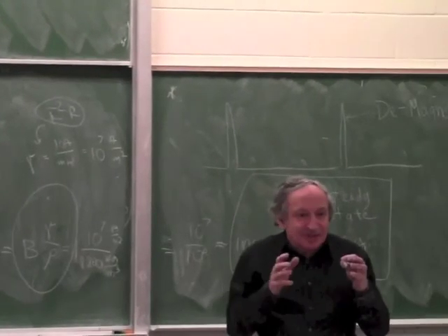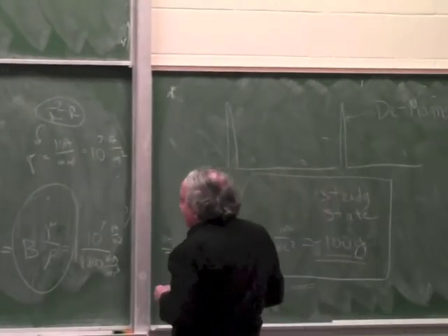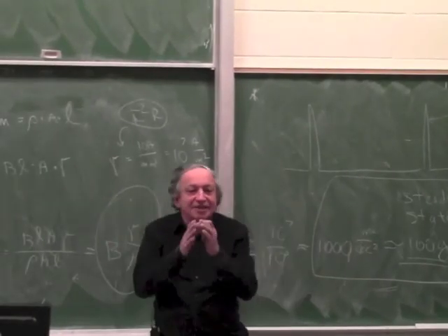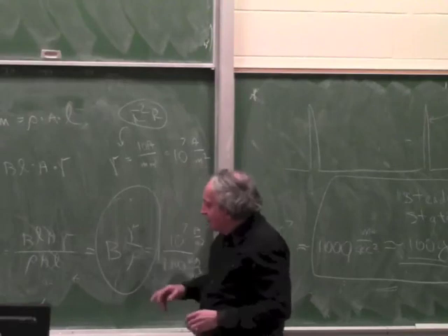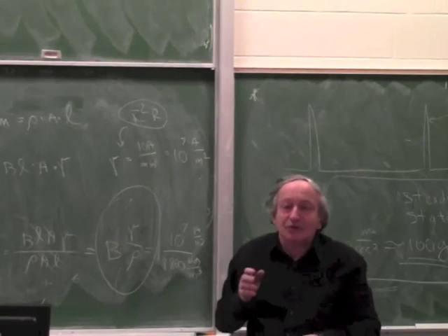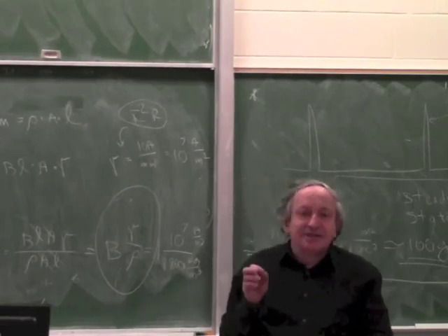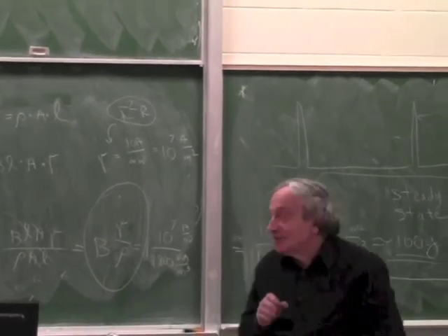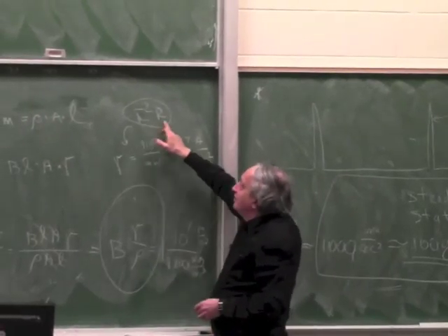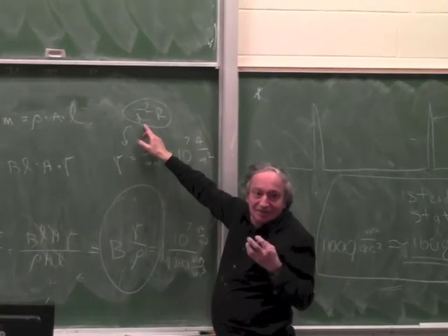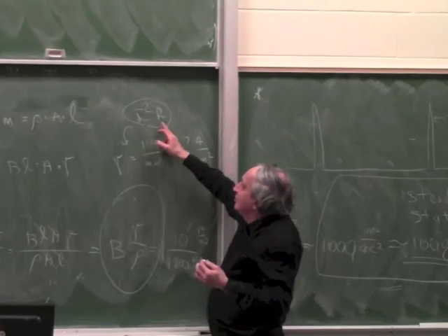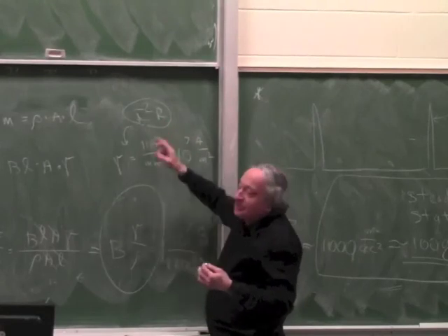It takes more space, because in order to carry the same current, you have to make the wires bigger. And if you make the wires bigger, you have to make the air gap bigger. So you lose a little bit on B. If you have the same coil with the same number of turns made of aluminum, to carry the same current, the wires have to be a bit bigger, because otherwise R will be bigger. You want to keep I squared R constant, same heat. So if I is constant and the resistance is higher, you have to make the A bigger to keep the resistance the same.